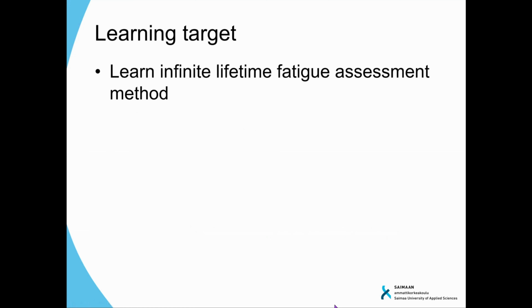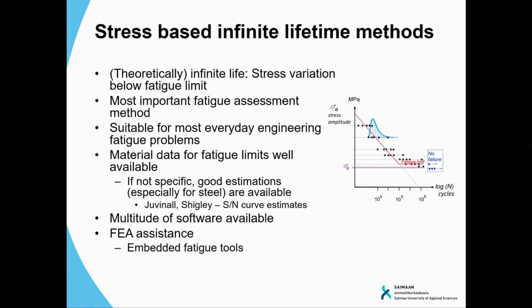Okay, for today we are going a bit deeper into the topic of fatigue in a way that now we learn how to dimension or assess or calculate structures against fatigue. And the approach we are learning today is the so-called infinite lifetime assessment method. What does that mean? When we speak about infinite lifetime, everybody understands that it is theoretically infinite because nothing lasts forever. But theoretically, the component for which the stress variation is below the fatigue limit will last forever.